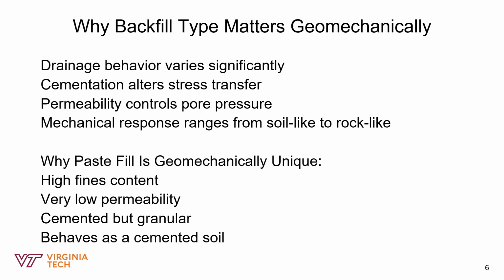So why is paste fill unique? Paste fill is special because it has high fine content. Remember the particle size curve we looked at earlier? Those fine particles make the material hold on to water, and so water cannot easily penetrate. That means paste fill doesn't act like solid concrete, and it doesn't quite act like loose soil either. It's kind of in between soil and rock. So it behaves as a cemented soil. It's like a hybrid material.